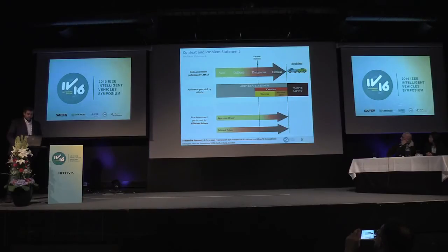So actually, if we want to suit most of the drivers, we have to push the decision threshold to the right, to dangerous and critical situation. So that will help to avoid false alarms for aggressive drivers. However, we will lose a lot of time for a relaxed driver.